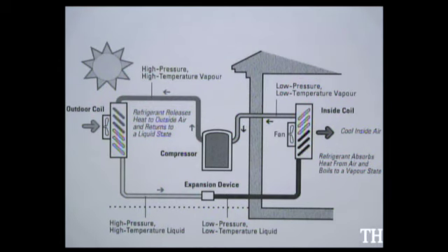The refrigerant now flows from the compressor to the indoor coil first, where the refrigerant now condenses and then flows to the outdoor coil, where it evaporates. You might be saying to yourself, how in the world am I going to pick up heat from outdoors when your temperatures locally here, 25, 28 degrees, have been the coldest? We're up north, you might be below zero sometimes. Well, R22 refrigerant actually boils at 40 below zero. So it can pick up heat from outdoors even if it's really cold outside.